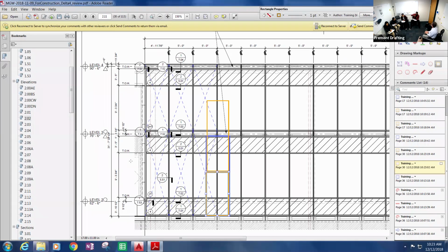So that's the wind load tributary area? That orange there is the tributary that's getting applied for wind load to that dead load anchor. Okay. And what's sort of funny, I'll call it funny, engineer humor. It's engineering humor, and I'm not even an engineer, but I'll laugh. This tributary area and this one, if it wasn't for the cantilever, if it was normal, is typically the same area. You just get to them in different places.